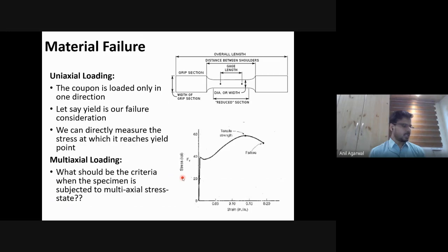Okay, I think I have the last 5 minutes. I'm sure all of you are familiar with this typical stress-strain plot. This is the yield stress. This is called ultimate strength. Then you have a failure point, right? And the failure point is what defines the maximum elongation, the percentage elongation, and that is what defines the ductility behavior.